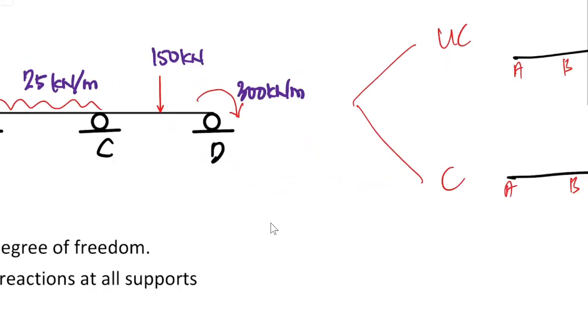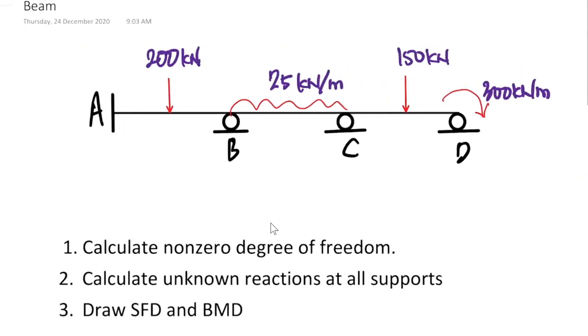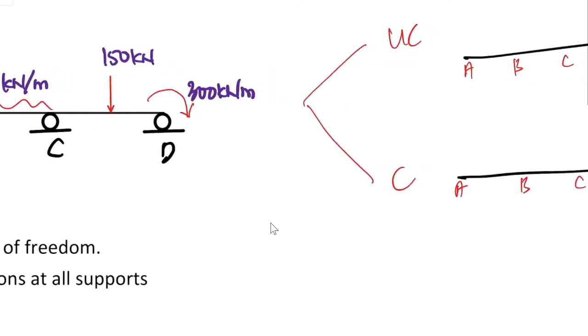At A, it is fixed support, and remember the degree of freedom for beam. We have to count 2 degrees of freedom at each node, in Y and Z direction. The reaction at the support that we get from a beam is actually the degree of freedom in the constraint system.